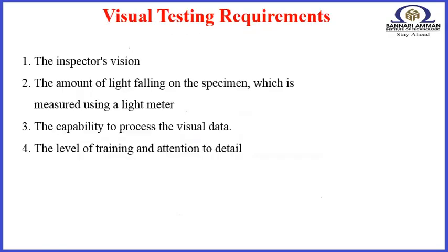Visual testing requirements. 1. The inspector's vision. 2. The amount of light falling on the specimen, which is measured using a light meter. 3. The capability to process the visual data. 4. The level of training and attention to detail.